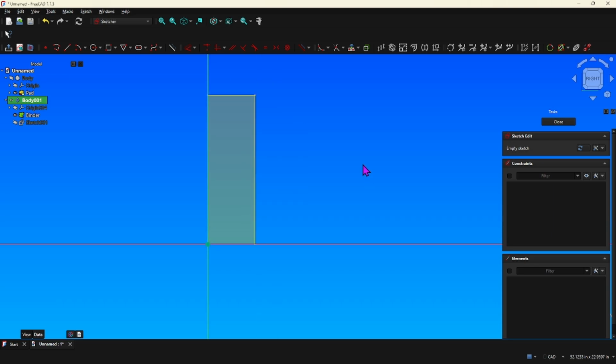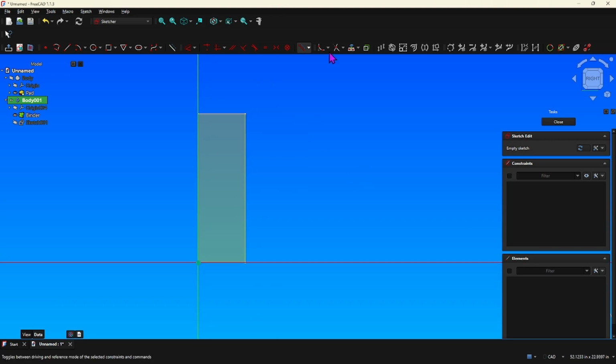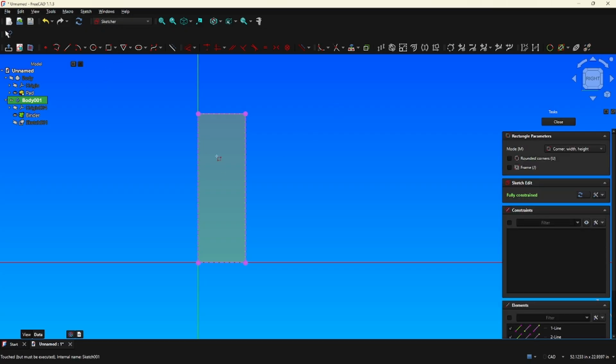All right. Then I'm going to use this command up here, the external projection, and I'll just select that shape binder, and it gives me reference lines that I can grab onto. I'm going to right click to get out of that. All right, now we're going to be accomplishing what he did in SketchUp.